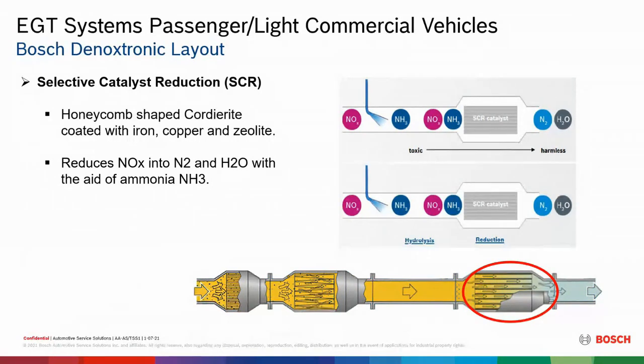But same thing, works the same. We're just going to go in this order for conversation. So the SCR, again, is a catalyst, with precious metals in there, like the rest of them we talked about. It's going to utilize some other components called DEF fluid that's going to reduce the NOx in the system. Again, high temperatures are required for this to work.